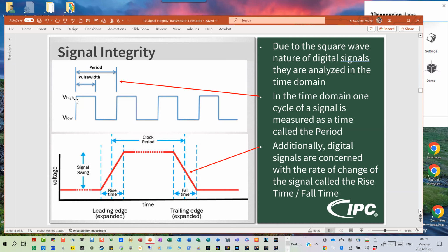But if I have a 10 megahertz clock, but my devices are trying to generate, say, a 100 picosecond edge rate, that means I probably have, say, 200 harmonics of frequency content to get that sharp of an edge rate. If I'm at 200 harmonics of 10 megahertz, that means I actually have frequency content up into the 2 gigahertz range, which means my originally simple little digital square wave has now got actual real RF frequency content in there that has to be dealt with.